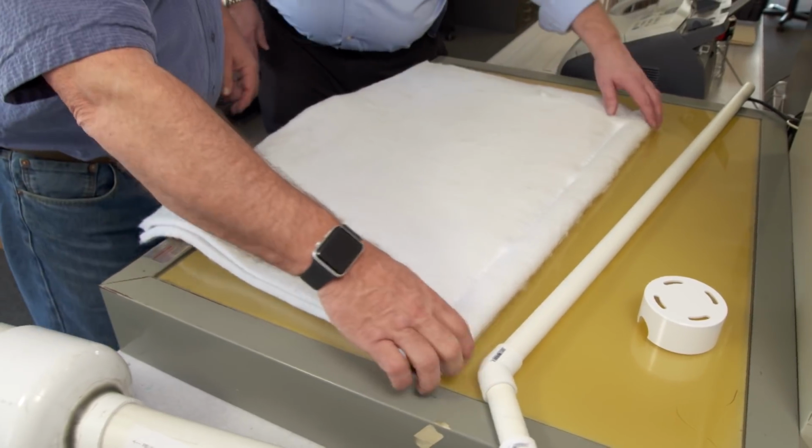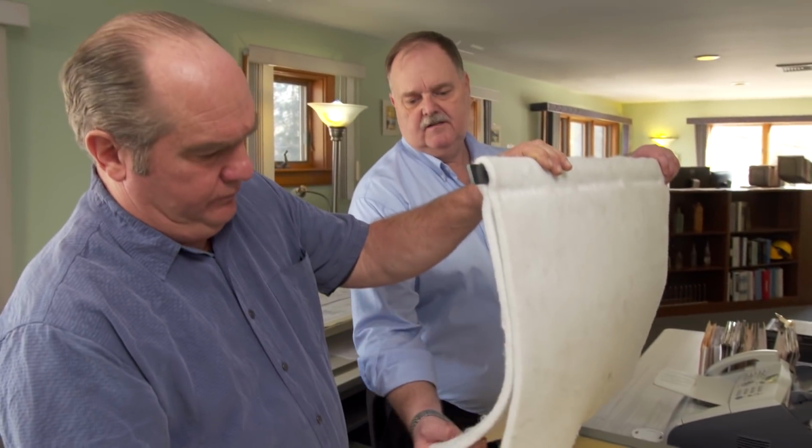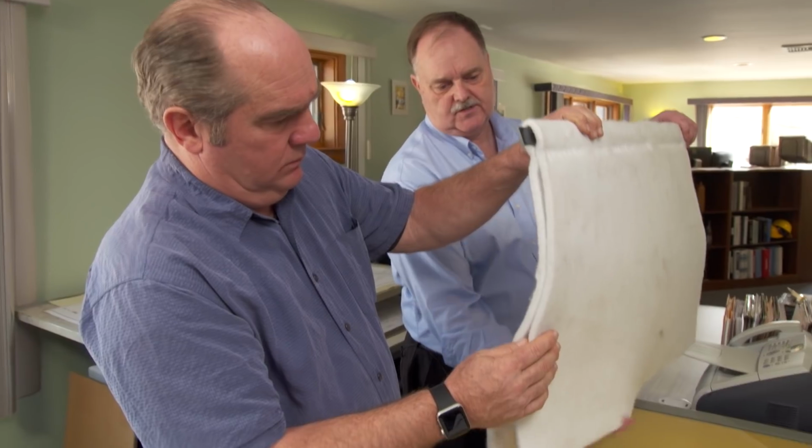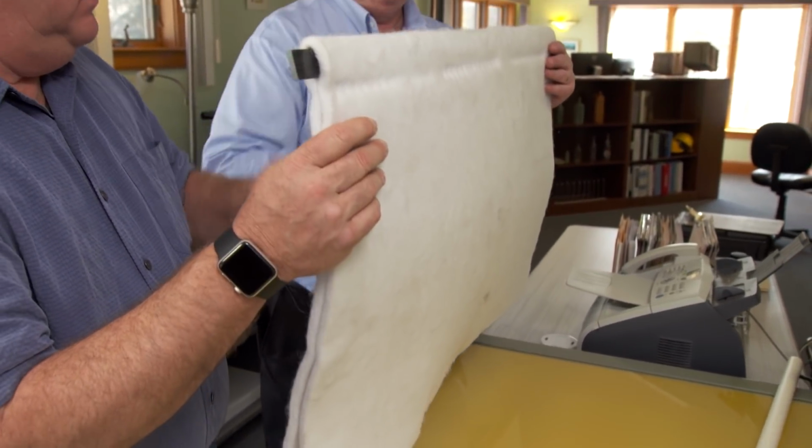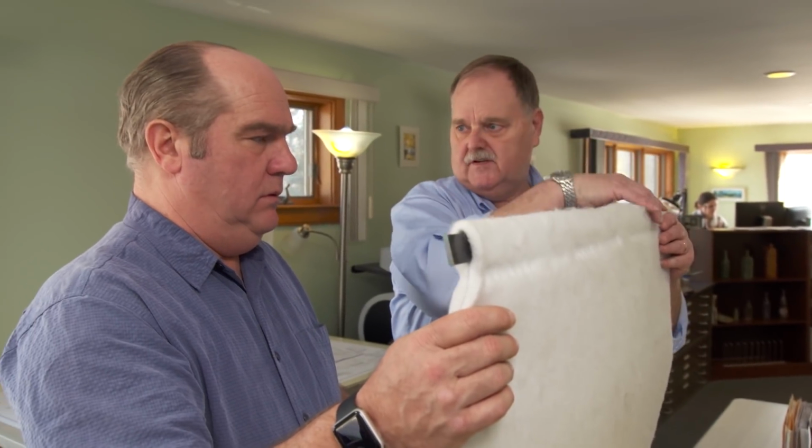I have one over here. All right. This is a hanging sheet. It's a textile fabric. There's 2 courses of it. And there's more than one in the... There's a number of these in there, okay, in the pod. And the effluent is distributed across the top of these evenly. Right. It just sort of wets the surface and drips down. And this is just loaded with bacteria? It's covered with bacteria. The bacteria love this. And the bacteria breaks down or converts the nitrogen? Converts the nitrogen to a different type of nitrogen.